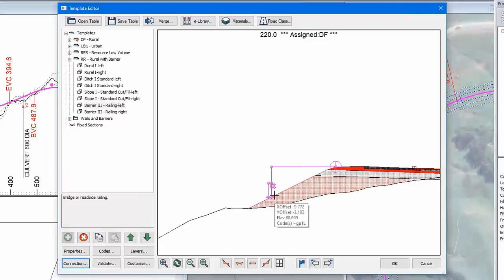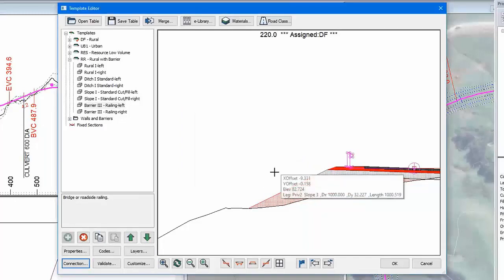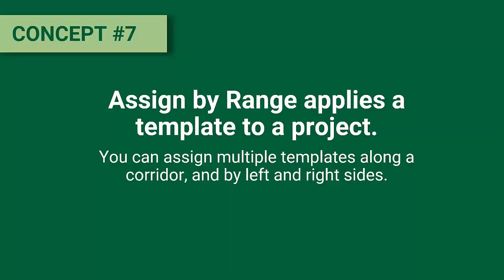So to recap this one, if you are building and compiling your template, the most important element is to consider your construction order. If something in your template doesn't seem to be working and making sense, think about looking at your order and be aware that you can change the connection point. Most of the time, you don't need to worry about changing these connection points to something other than the default, but it is an option that you have.